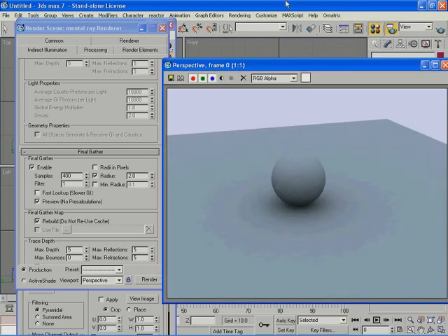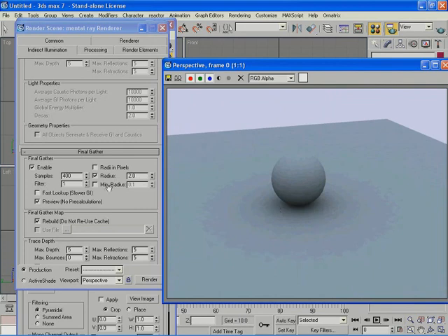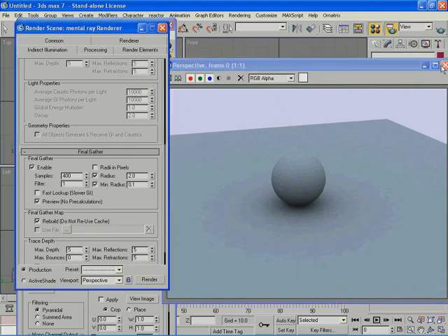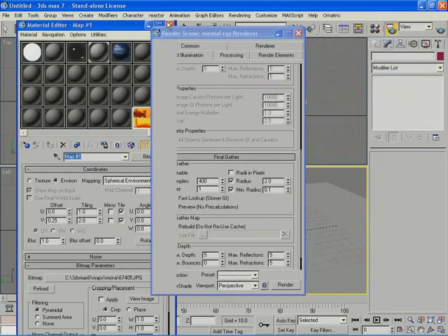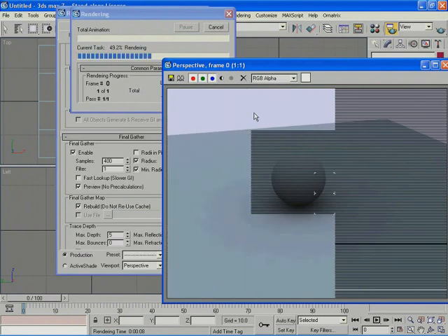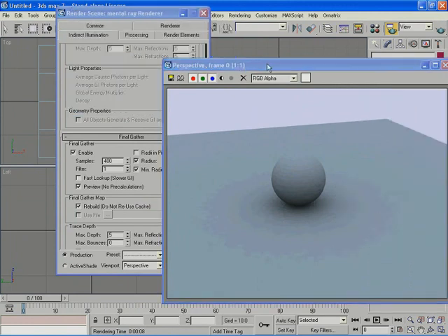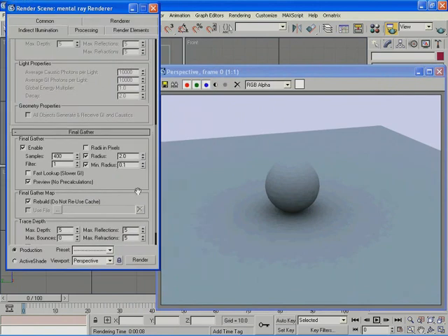So, if I set the minimum radius to 0.1, and here I have the render time to be 8 seconds, if I render this, I'm still going to have 8 seconds, but I would activate the minimum radius to get finer detail. So I'm going to go down to 1 for the maximum radius, and this will make the occlusion even finer and therefore more realistic.